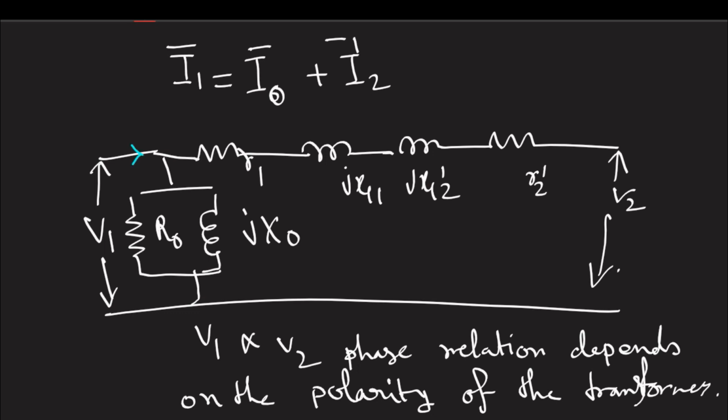And how these two currents are not violating things: previously I was trying to give you a flavor that the additional primary current and the demagnetizing current, when we add them together, considering their direction, the algebraic sum gives a very simple thing, that is the magnetizing component of current required to maintain the core saturation. But there is also nothing wrong to represent it like this, I naught plus I2 dash, which is also reflecting the magnitude.